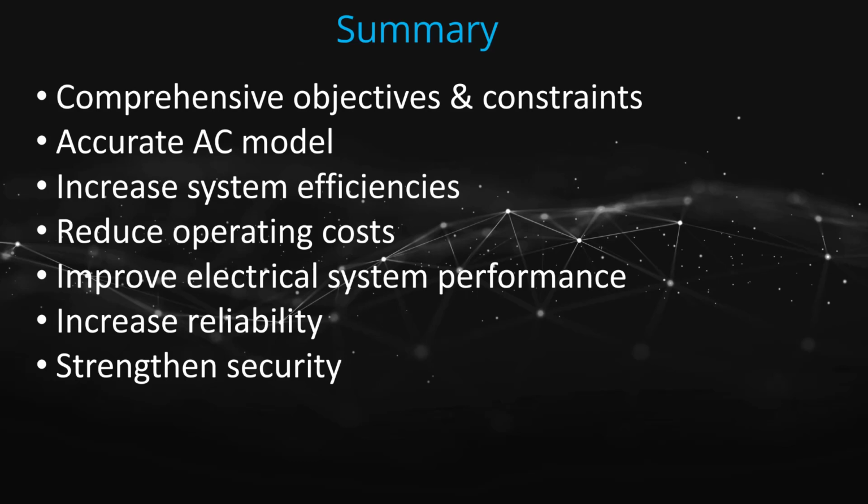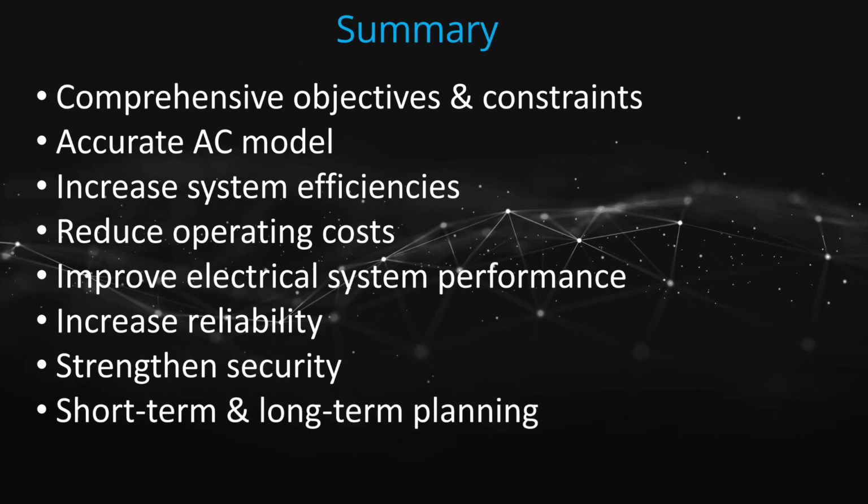By optimizing the reactive power, you can strengthen system security, and you can use OPF not just for short-term purposes but also for long-term planning objectives, where you can include scenarios such as additional load growth as well as new substation additions in the system, and of course use the OPF calculations not only in system design but in operations as well.